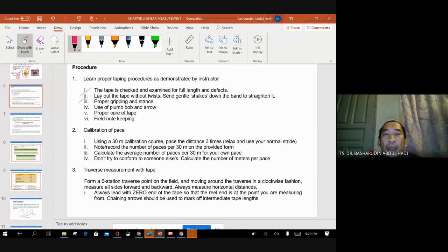Or sometimes you give a signal to your friends to lower the tape. Normally points A and B are not different in height, but if there is a vertical difference, maybe point A is slightly higher by 2 meter, how do you want to straighten it? It's quite difficult because you must stand up and pull the tape, and sometimes if the distance is 10 meter, maybe you need 5 manpower to straighten it.